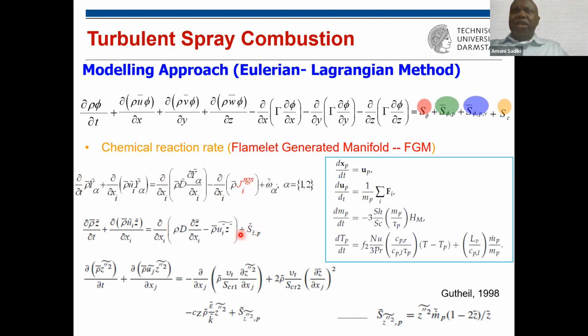Then I have told you that in this case, the mixture fraction is no more a conservative quantity. For single-phase combustion, it is a conservative quantity, but not for two-phase flow. And in this equation of variance, we have an additional term which accounts for the phase change. This was given by this expression as I showed. So this is the set of equations we have to solve.